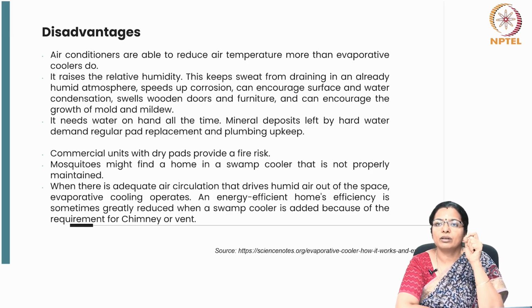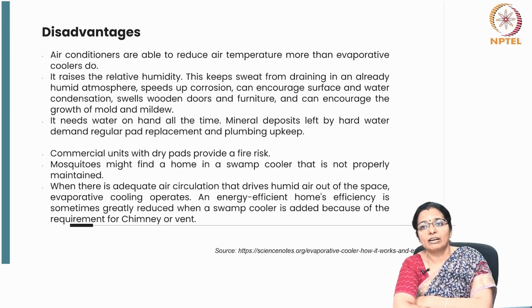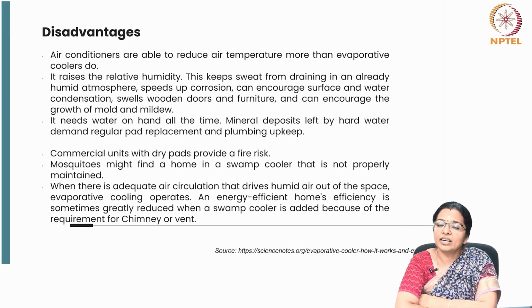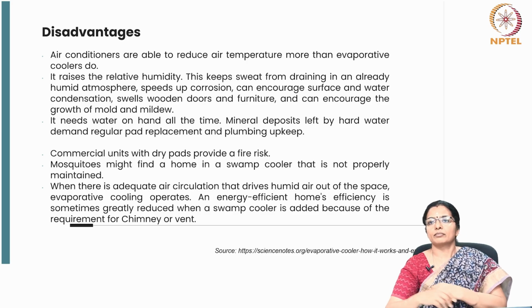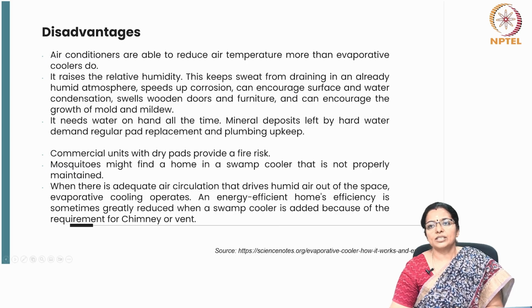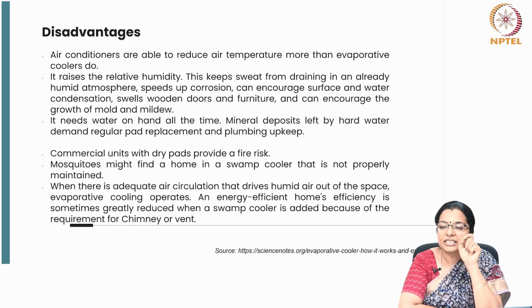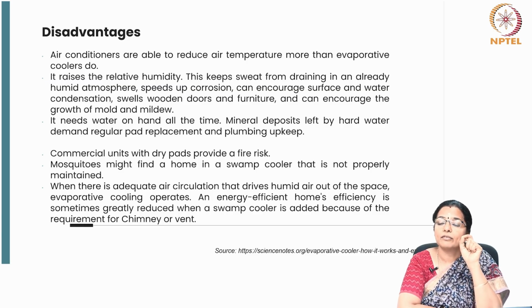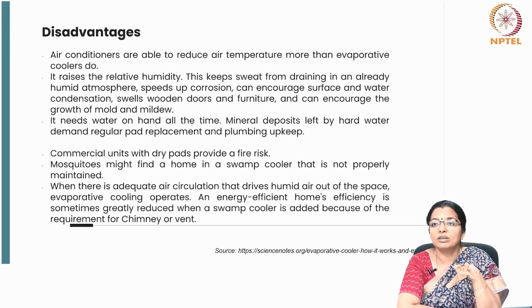It needs water on hand all the time. Mineral deposits left by hard water demand regular pad replacement and plumbing upkeep. The commercial units with dry pads have the small disadvantage of being fire prone. Mosquitoes can become a huge nuisance if the home has a cooler which is not properly maintained.